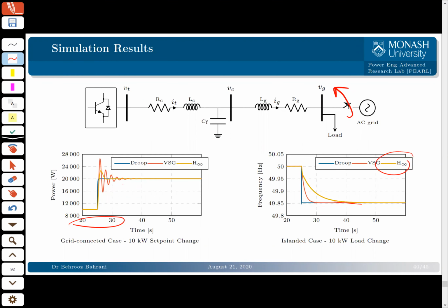You do a test, obtain the model of the system, and then do an offline optimization for control design. You get the coefficients of the controller, which can be a transfer function, depending on the performance you're after, first order, second order or third order, and that's it.